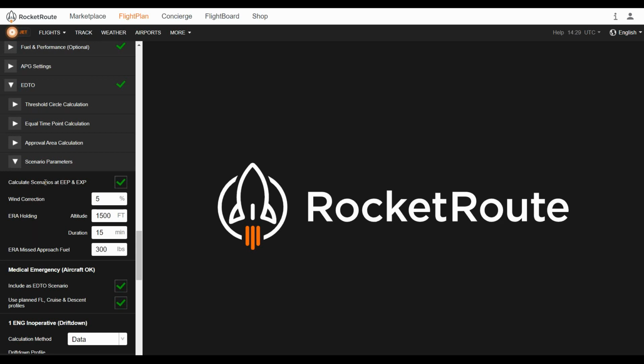So you can either include them in the EDTO summary or exclude them. Then we have wind correction, which is a percentage value. In addition to that, we have ERA holding, so you need to define the altitude of holding and the duration of the holding, and ERA missed approach fuel. This is also included, so you need to define the fuel value for this.